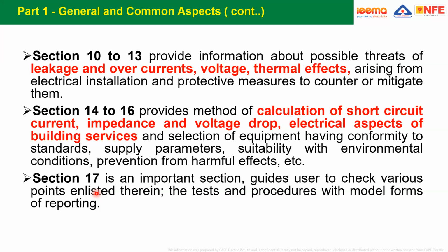Sometimes people ask, why not audit? Actually, we don't use the word auditing in the standard because auditing is a job which is carried out on sampling basis. Auditing is not carried out in all the circuits, whereas verification is a much clearer word. Verification consists of inspection and testing, and verification has to be carried out in all the circuits because we are talking about safety.